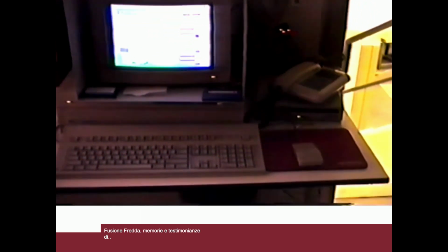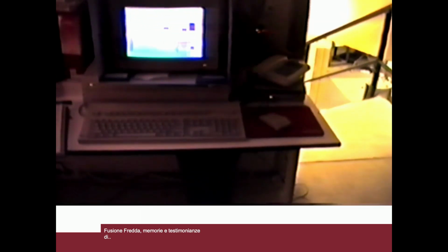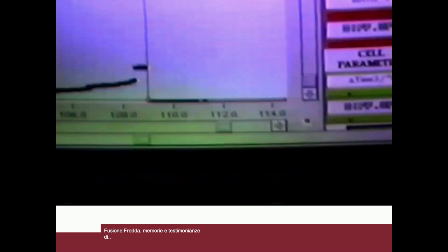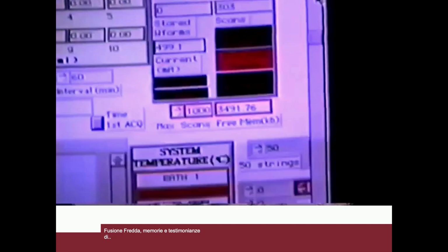This is another Macintosh FX that also runs with a LabVIEW program for acquiring all the parameters of the cells in the experiment and controlling a number of functions. All this takes place through the connection via interface with the data logger. The data logger controls the maintenance of the electrolyte level in each cell through the laser beam level sensor. Another important control is the rotation speed of the pump, which ensures the constant flow of thermostated water in each cell. The accuracy of flow calorimetry depends greatly on this.